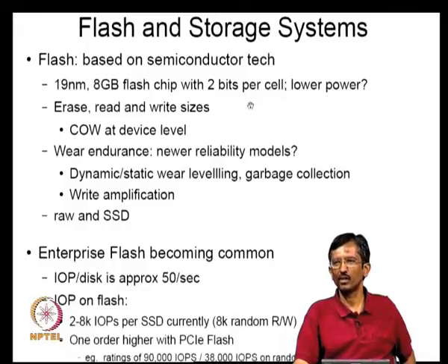but it has more errors. So you need a good amount of error coding for it. Reed-Solomon coding or other types of coding are also being used. For example, you might have some XORs, some parities horizontal, some parities vertical, all kinds of things people are designing. You can have RAID also on top of these things. So many designs are coming out. One thing about this also is that it has the potential of being lower power.